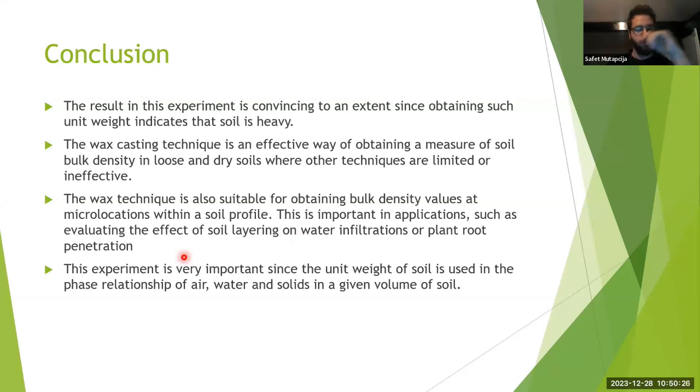Not really a simple one, but if you're asking about the soil compaction, like the optimal one, there is one thing. Every soil can be compacted to some maximum level of compaction. There are two tests. One is CBR, California bearing ratio, and one is the Proctor test. Two different tests, and you usually do them at the same time, but the Proctor test is the one you're going to use to get the optimum moisture content.